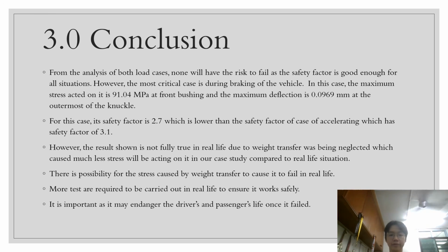In conclusion, from the analysis of both load cases, none of them will have the risk to fail, as the safety factor is good enough for all situations. However, the most critical case is during braking of the vehicle. In this case, the maximum stress acting on it is 91.04 megapascal at the front bushing, and the maximum deflection is 0.0969 mm at the outermost of the cone curve. From this case, its safety factor is 2.7, which is lower than the safety factor of the accelerating case, which has a safety factor of 3.1.